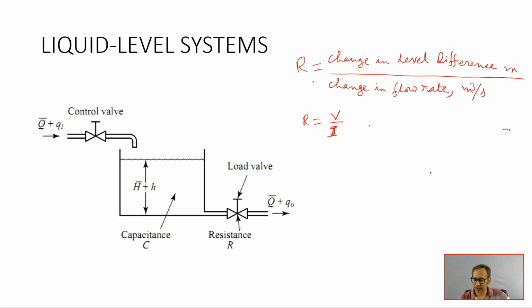Now, at this particular restriction, you can say that this flow rate Q is proportional to this height, this level of the water. Let us say this is the water level in this tank. So, that means Q equal to some constant of proportionality into H. If you consider this linear resistance, this linearized system, although it is a turbulent system, we have linearized about the operating point.